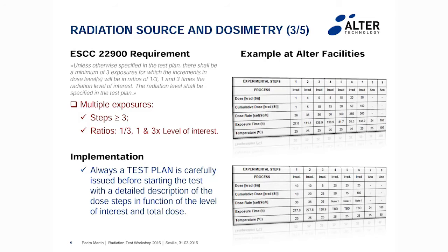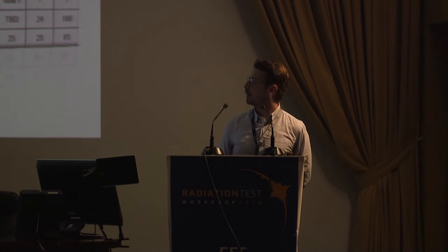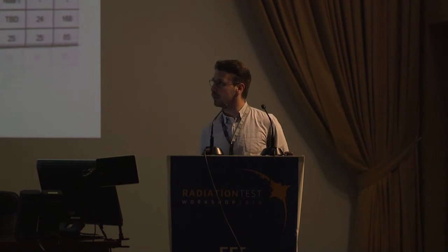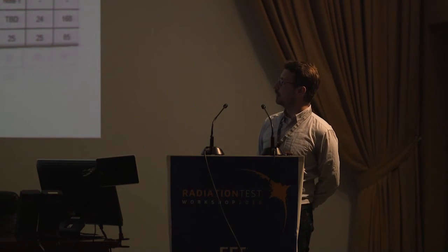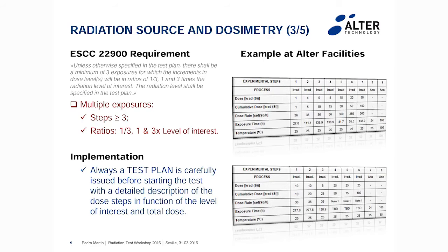Another requirement is about the dose steps. When you need to perform multiple exposures, you have to choose where you are going to interrupt the radiation test to perform the electrical measurements. In this case, the test method is very easy to comply with, but I would like to emphasize that it's very positive to show flexibility in the schedule.